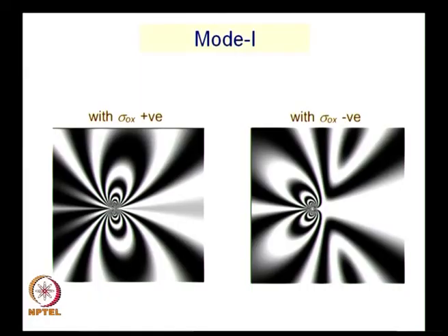Suppose I have that broad enough and a specimen long enough like this, and you have a crack and loading is applied, you find the fringes are backward tilted. So, people are happy with Irwin's solution: by changing sigma naught x suitably as positive or negative, they could analyze short cracks in SEN specimens and short cracks in the case of RDCB specimens.